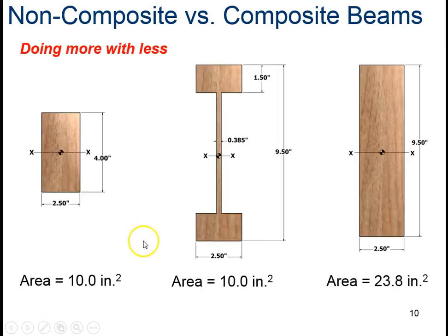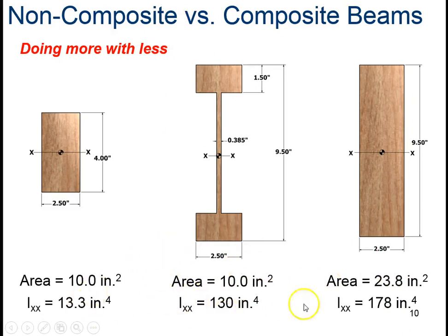And we use these different beams because when they have the same cross-sectional area, they have the same weight. But they'll have different moments of inertia. Which is better, a bigger moment of inertia or a smaller moment of inertia? Well, the bigger moment of inertia has less bending. So these two have the same area, so the same weight, the same amount of materials being used for them, so probably the same cost for these two.